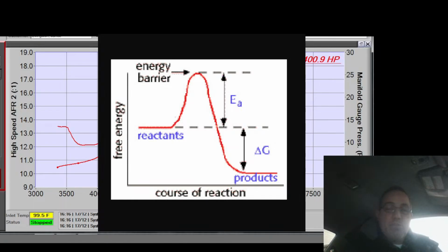And you see that in your ignition advance tables, right? When I am at cruise, all the molecules are really far apart. I got to light this thing off at 35, 50, 60 degrees before top dead center because it's got to burn and then needs time to transfer the energy to the next one, and the next one, right? It takes a long time for the energy to get to the neighboring molecules. And so I have this really advanced ignition curve.